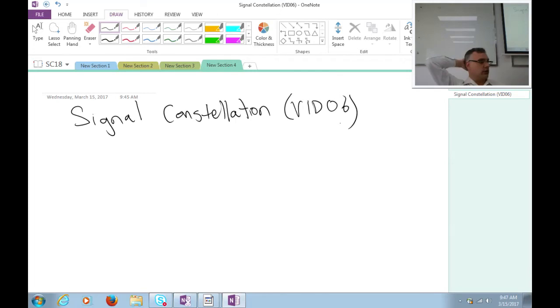There'll also be weather, right? Now we're talking about high enough frequency where rain fading, even a modest rain, might add 1 or 2 extra dB, which will make a difference in the satellite link. And so the signal constellation for video transmission needs to be adapted to make the most of the radio spectrum. That's different than the first DVB standard, which was simply QPSK. Let's use QPSK all the time for our transmission link and hope that's good. And if it works for the worst case scenario, it'll work for the best case scenario.